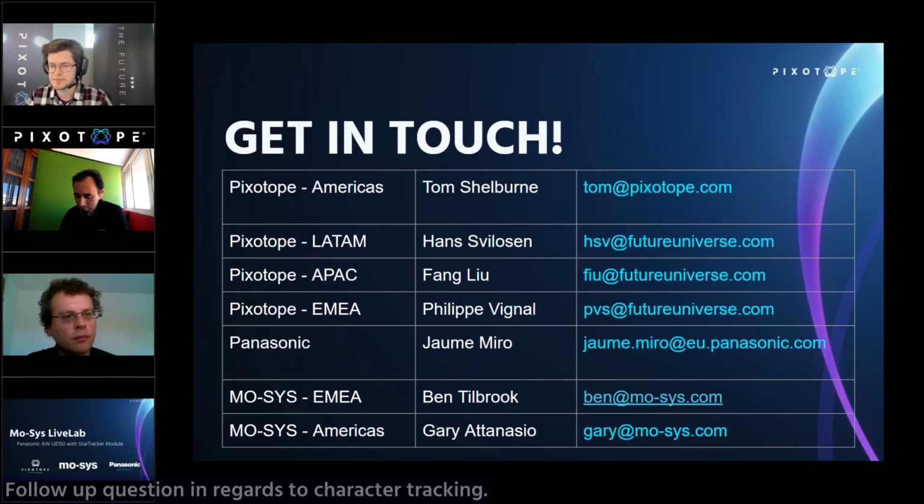We have covered this in previous Pixopalooza sessions, as well as some of the material from last year's NAB. But the answer is more or less what our friends at Mo-sys just pointed out. You have your plane, you have your person, you get the 3D position of your person by tracking him, you feed this data to your plane, and now your plane is able to move around freely. Of course, the plane will always be facing the camera, so we don't have to worry about rotation. It doesn't matter how you get it, but if you're able to get the 3D position of your talent into Pixotope, we can use that to offset our composite plane. Also worth keeping in mind that we are projecting onto a composite plane because that's the most typical use case, but the composition plane can be any shape. There are use cases where, if you're using a Steadicam, for instance, and need to be able to more dynamically move around a person on a green screen, you might want to use a cylinder or some other kind of geometric shape instead.